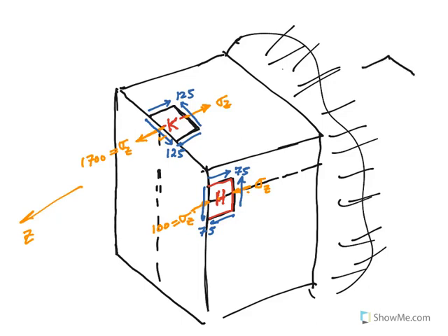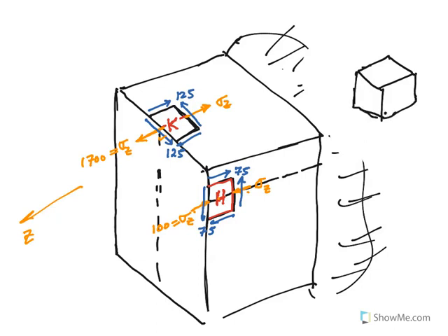So for example, if you look at point K, and you want to make this a three-dimensional stress element, let me erase part of this here so I can show you what's going on. Okay, so this is what we have. Basically what I'm doing, I'm just making this a three-dimensional stress element. So you see, basically you have sigma z, let me put the same color, that's your 1700. As you could see, this point is less critical compared to the other point, H is more stressed.